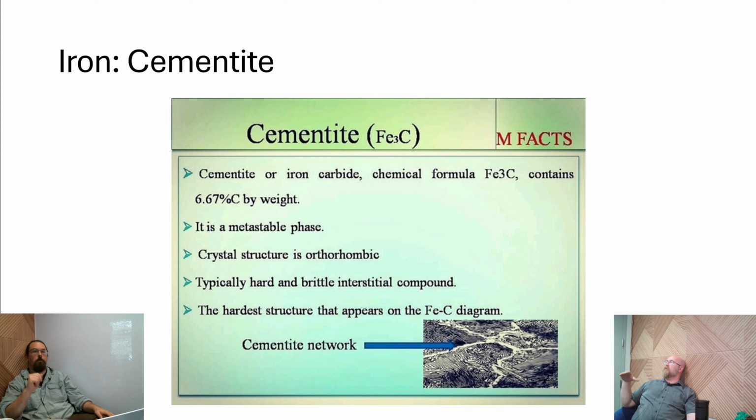Where you have these cementite networks laced back and forth in between layers of ferrite. And you can see here, in these valley-looking structures, that recurring layering pattern of ferrite and cementite happening. And these cementite networks being pointed at here are a more pronounced continuous form of cementite.